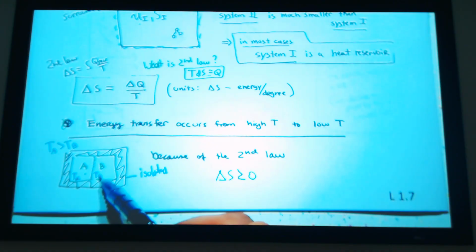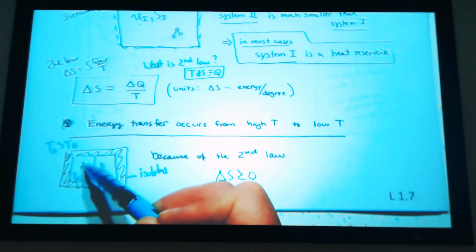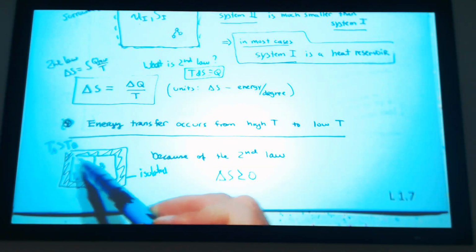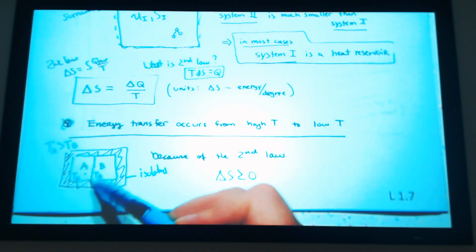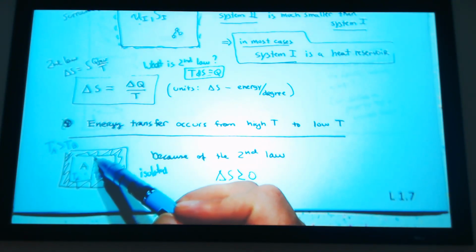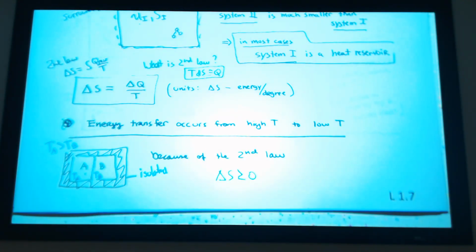This has a temperature, this has a temperature, this has a pressure, this has a pressure. I have a spontaneous boundary here. There's an entropy of A. There's an entropy of B. If I say that this is basically just a fictitious boundary where I don't let anything transfer for some snapshot in time, then entropy of A plus entropy of B equals the total entropy inside.